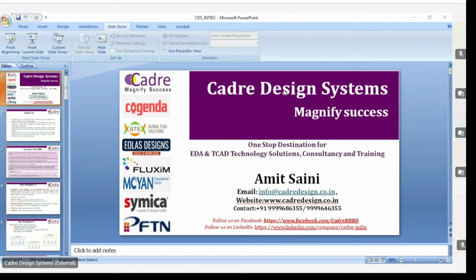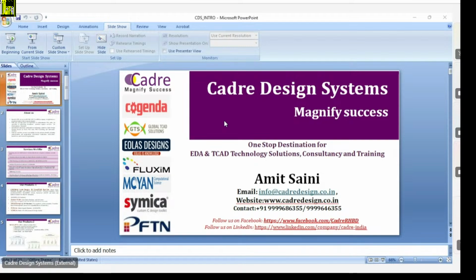The Visual TCAD environment also supports a radiation hardened module. For this, we have a separate tool set that we call the radiation hardened module. Using that, you are able to do single event effect and TID simulations on your single devices as well as on small circuits, like an SRAM cell, a storage cell for a D flip flop, or any register. So your storage device will be a radiation hardened storage device.